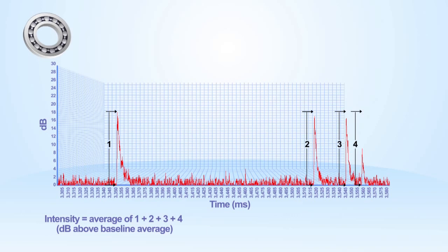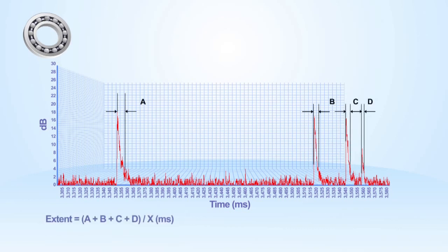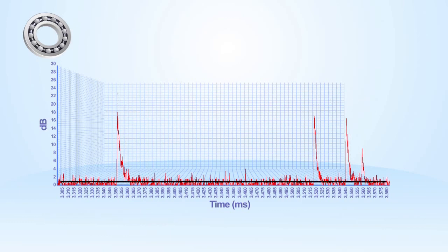Intensity determines the average amount of activity occurring over the measurement time frame. This parameter is often used to quantify the rate of degradation of a rotating element. Extent is the percentage of the cycle in which activity is present. It is very useful for detecting start and spread of generalized damage. dB level. As in standard mode, dB level measures the frictional activity present. However, at slow rotational speeds, generally the values will be minimal, possibly even 0 in certain circumstances. When trending data in super slow mode, dB level is generally at a level of 4 or below for an undamaged bearing.